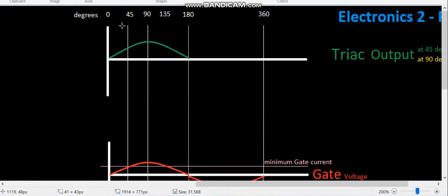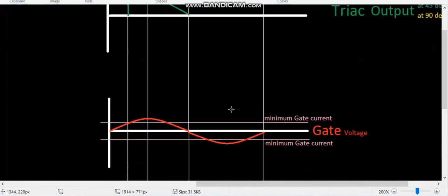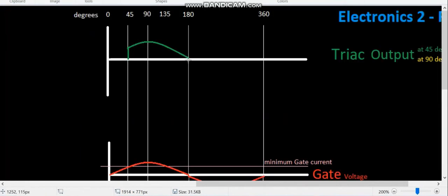So let's take a look at what that would look like again over here. Again, the reality is that if that threshold isn't being met, then none of this is conducting. This isn't going to be here. So we're going to end up, again, having this line where that firing angle delays the conduction to that point. And then on the negative portion, as it cycles below this zero threshold, it turns off, but the negative will flow as well here.